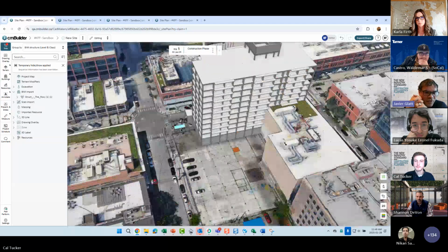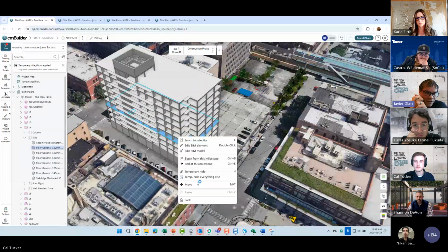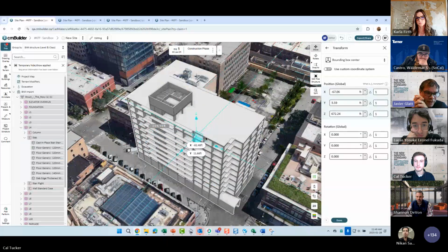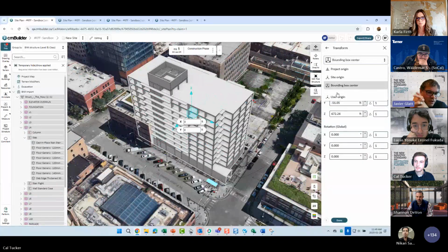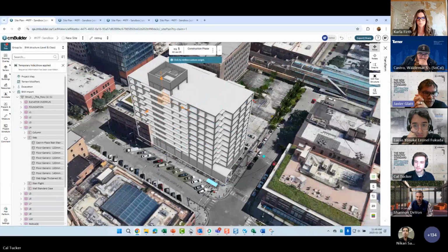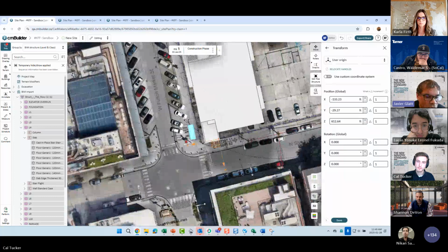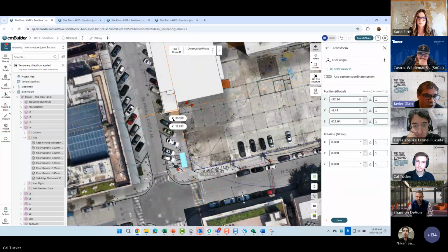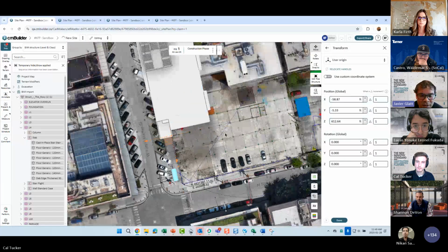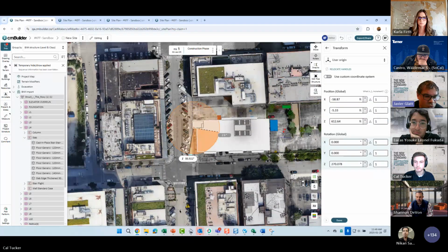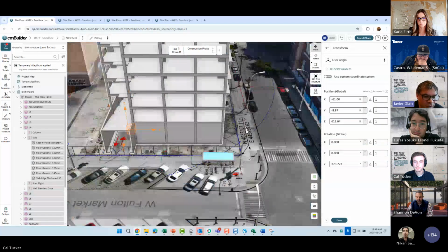All right. So even if it's not geolocated, like in this case, very easy to position a model. You can just use a local reference from a drawing, or just that overlay from the satellite view. Position the model with coordinates. Now, one thing as Cal's doing this, he's going to locate the structural model, and if you have additional models, architectural models, MEP models, you can snap the models to the first one. So if you don't have it geolocated from the file, you can just locate a model and snap all of them to there, okay? So you get the idea.